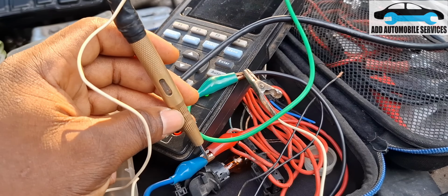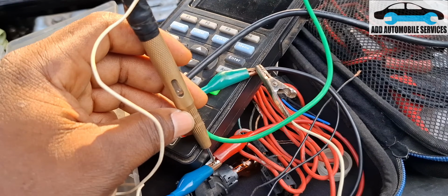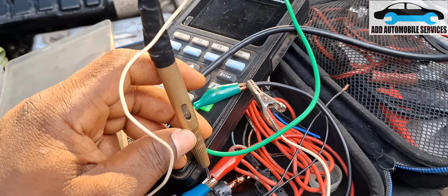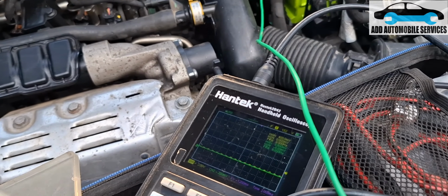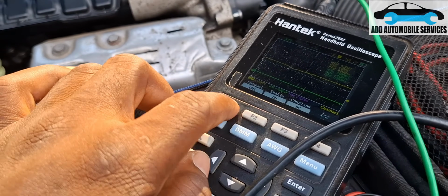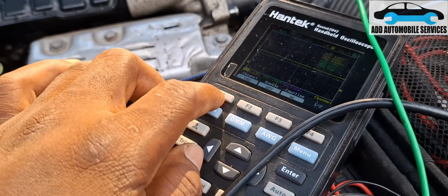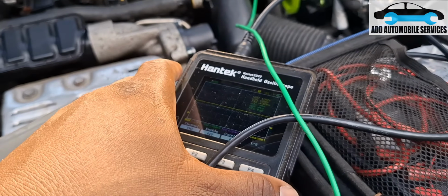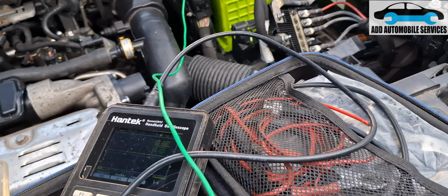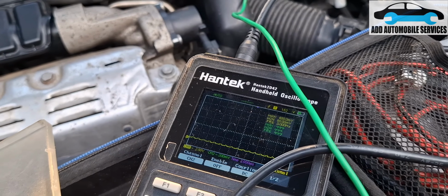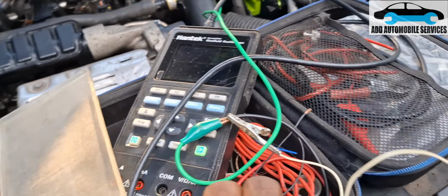So you can see this is my power line. If I test it, it should be able to turn on. You can see it's not turning on, and my 5 volt line is off. Let me turn off the channel 2. Okay, so you can see my test light just went off. When I release it, it goes back to 5 volts. So that means it could be a signal line.